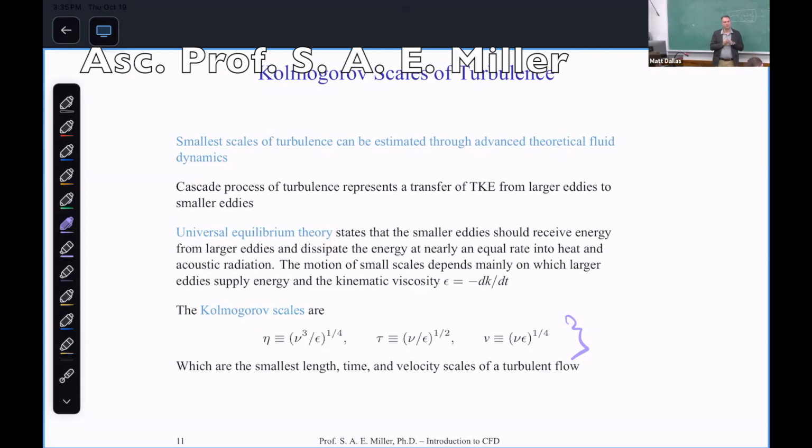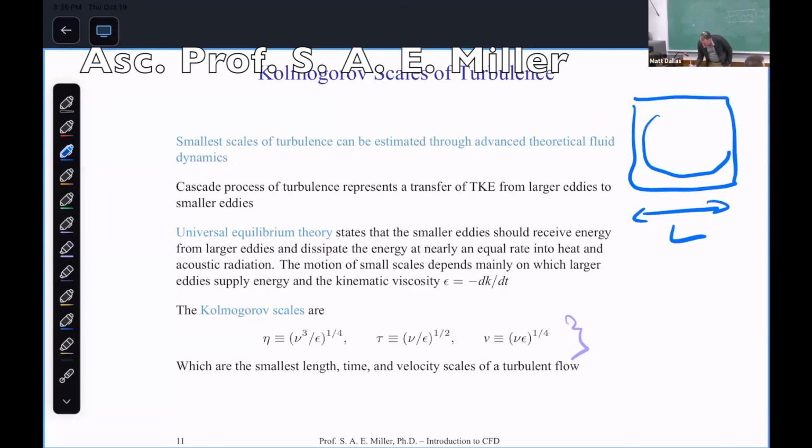He took the Navier-Stokes equations and did a bit of a rearrangement and a statistical analysis for what we call high Reynolds number, high intensity turbulence. And this is the problem we talk about today. Let's say we have a little box in the atmosphere. And the length of the box is something like L. And the biggest turbulent eddies in the box are maybe about L. And then there's tiny, tiny little turbulence in there. And that length we'll call eta.